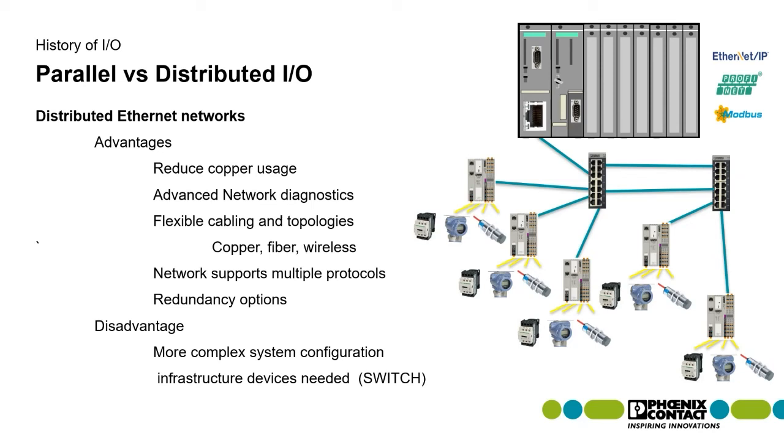These are all terms that switches support inside of their network. And these different protocols make what they call recommendations that most of the time you really should follow, but they're not a hard requirement. So you will see, oh, look, my switch is rated for Ethernet IP. My switch is a Profinet device. Basically, it has settings, and all the settings are set for Profinet, or for Ethernet IP. It's pre-configured to function ideally for the network it's supposed to run on.